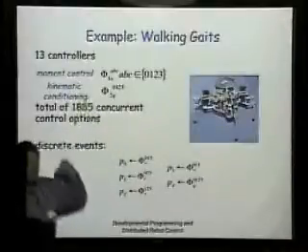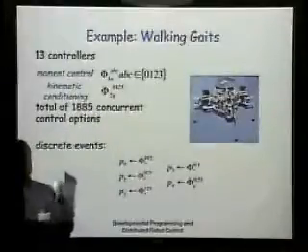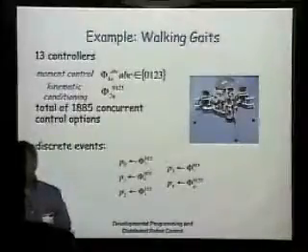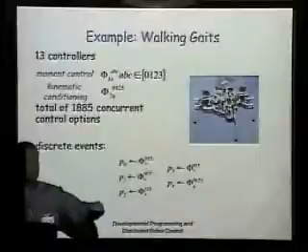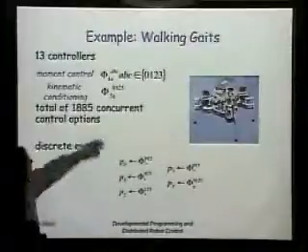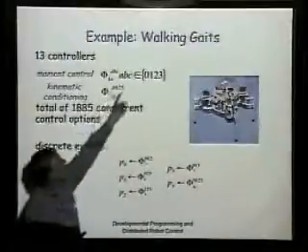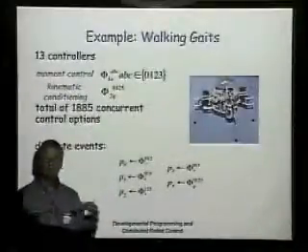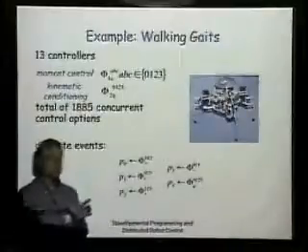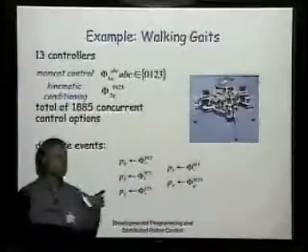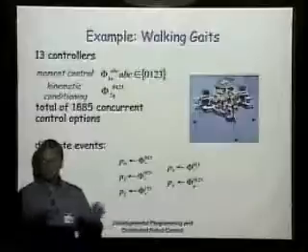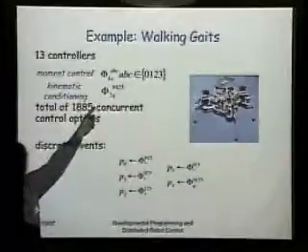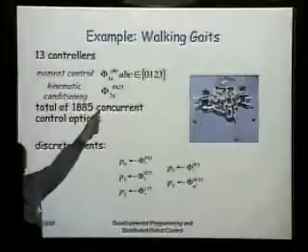When it hasn't converged, it asserts a predicate value of 0. When it has converged, it asserts a predicate value of 1. It says that tripod is now a possibly stable tripod, right? The kinematic conditioning takes all 4 legs and moves the heading of the body so as to move all 4 legs simultaneously back towards the middle of the space where they're isotropically conditioned, forces and velocities equally well in all directions. That's it. Those are the only 2 instructions I'm going to allow this robot to explore in this developmental stage.